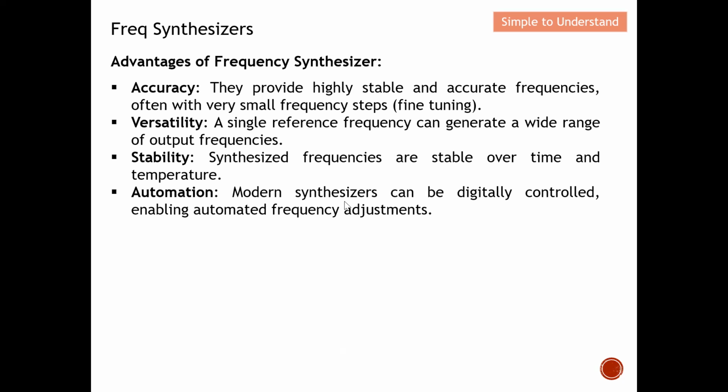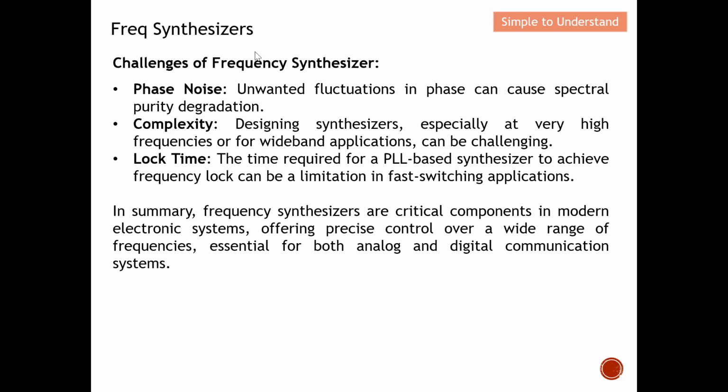Automation: modern synthesizers can be digitally controlled, enabling automatic frequency adjustment. So nowadays with technology advancement, especially the digital ones, they can automatically adjust to produce the desired frequency. Coming to the challenges of frequency synthesizers, firstly the phase noise, which is unwanted fluctuation, meaning the phase can go up and down, and this can cause spectrum purity degradation, which means some undesired effect on the frequency spectrum.